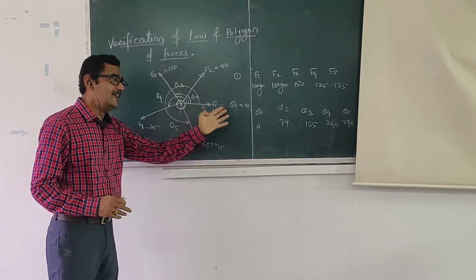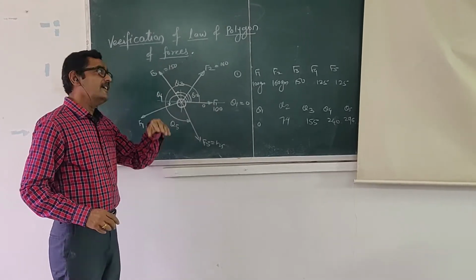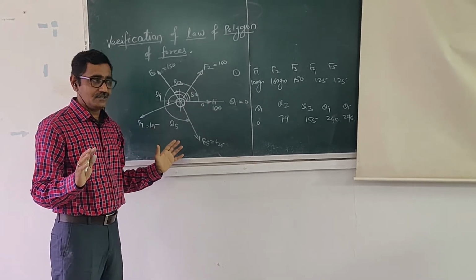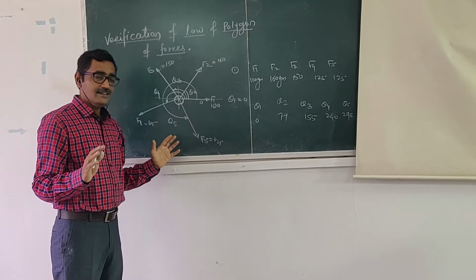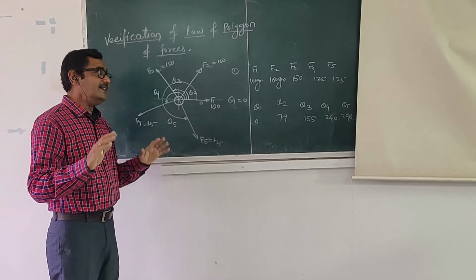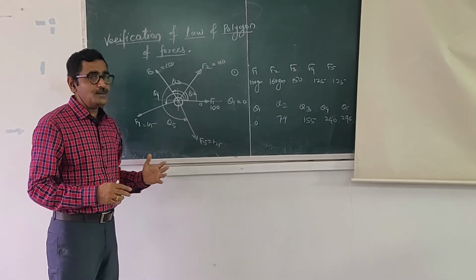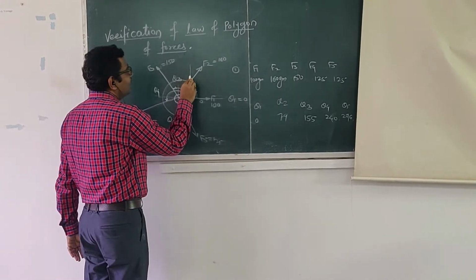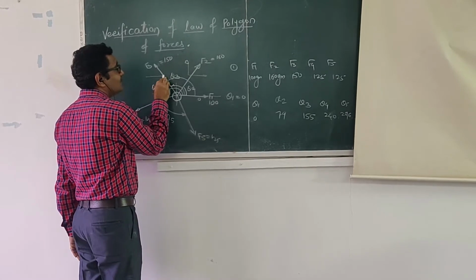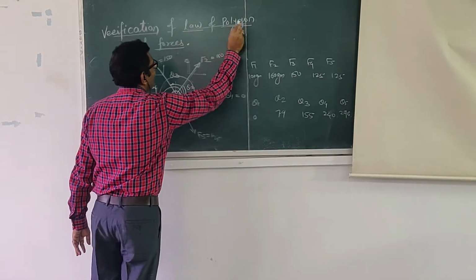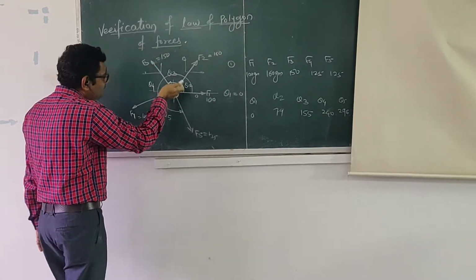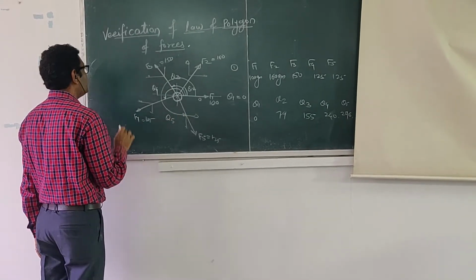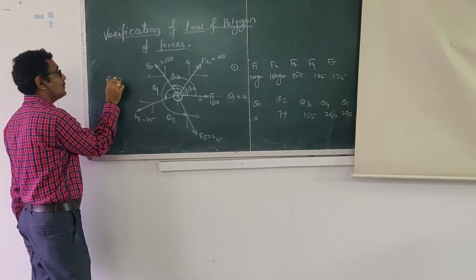We can have the same reading, or I can take a different reading, and by using a different reading I can explain how we can do the calculation. Any doubt? By plotting the force polygon, that is the graphical method, if you observe that the resultant is not 0... Similarly, if you find the resultant of these 5 forces analytically by resolving the forces, the resultant must be 0.